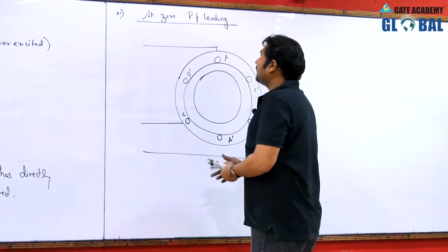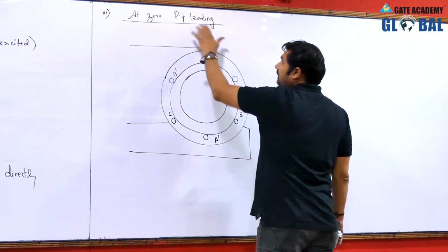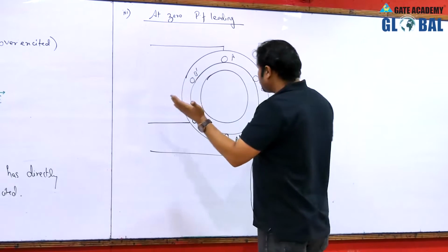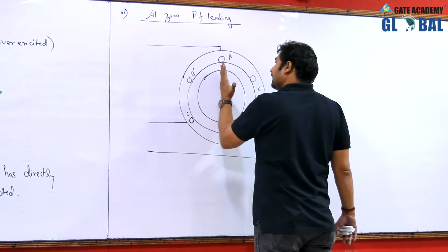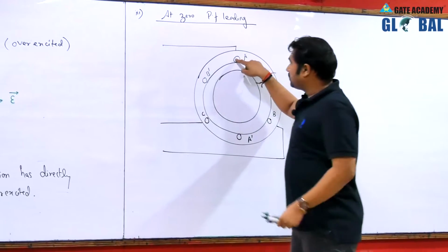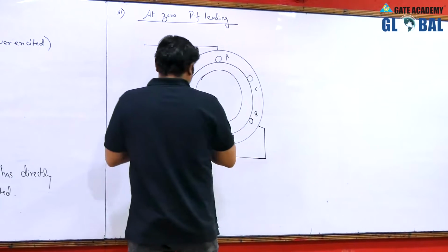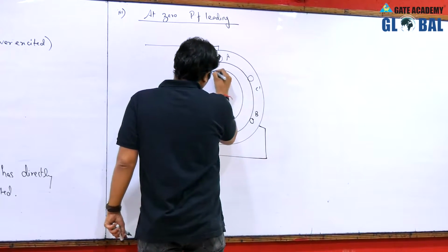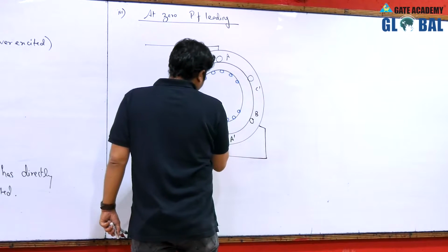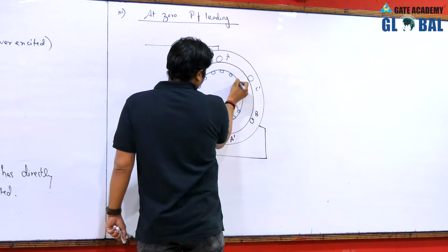Is it okay? So, whenever your power factor is zero lagging, it means you have to provide the opposite for zero leading, that is, a lag of 90 degrees to the field. Automatically it is going to be satisfied, because it is not possible to represent the lag and lead in the current in terms of dot or cross. So, please observe here, at zero power factor leading, the current starts flowing in the conductor 90 degrees before this induced EMF.